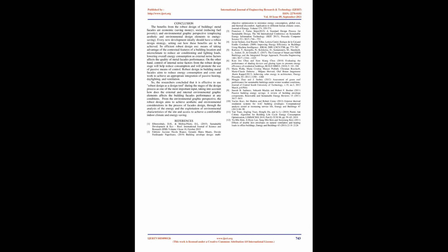Another detailing energy simulation performed during thorough building envelope design stage made appropriate recommendations on the facade, glazing, shading devices, lighting control options, and natural ventilation to be employed to realize energy-efficient buildings. Besides the design of the external shading devices installed, the type of glazing used impacts the cooling load of an air-conditioned building. Different glazing will have different properties that determine the amount of solar radiation emitted into internal space as well as the amount of heat being conducted away. Qian-John Chua and Xiaoqiang Zhou, 2010.